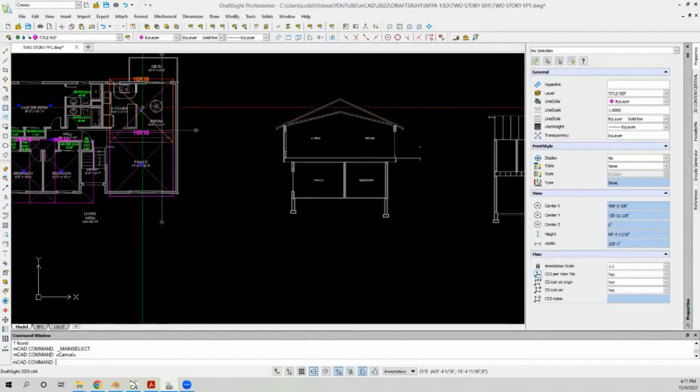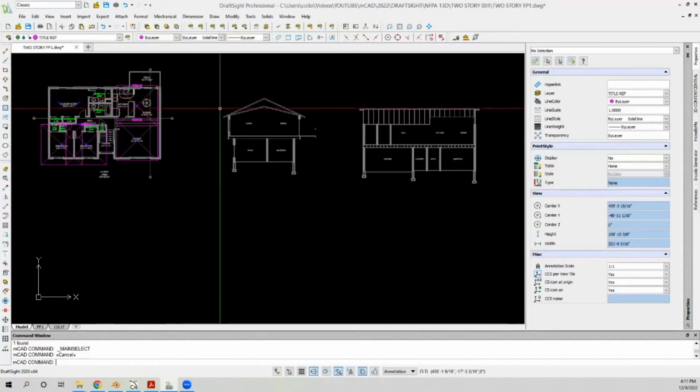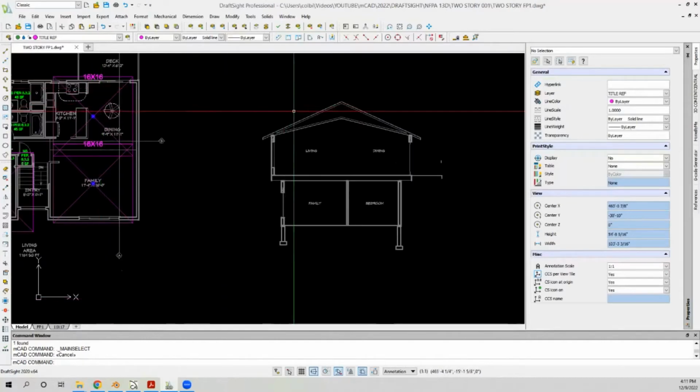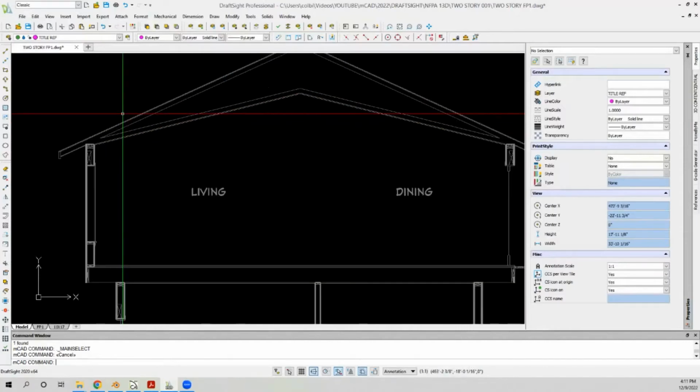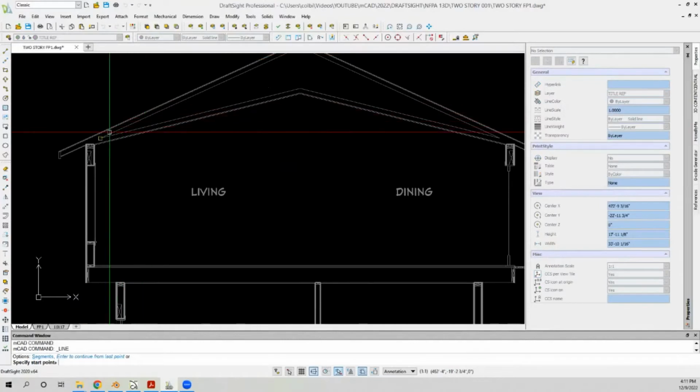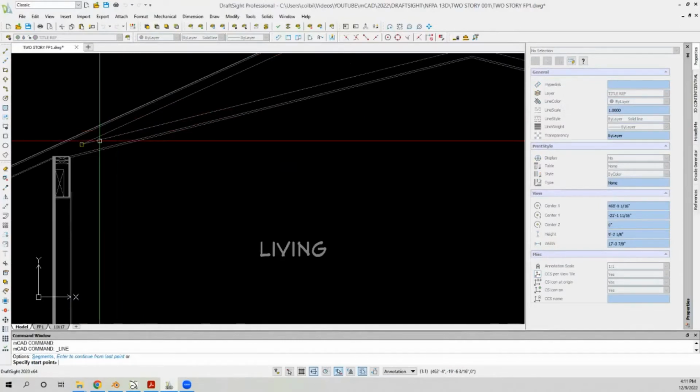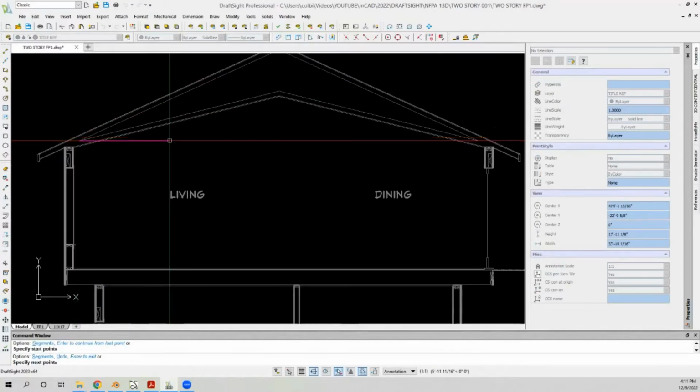And so to figure out our maximum spacing off the wall, you would go to your section here, and we're going to just draw a construction line. This line right here is the same as the slope of the ceiling, so I'm just going to go out 12 feet.